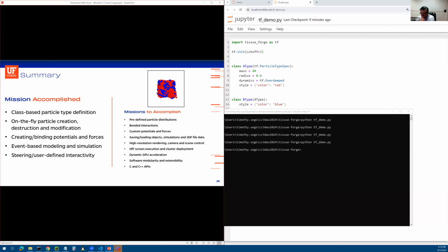So you go at this with finite element analysis, and it's an incremental force that they apply, a tiny little incremental force that they apply to get where they're going with their model. And every time you hit it with an incremental force, it kind of changes the whole shape of the object. So it gets out of control in a hurry. And so I've discovered that if you just take the first iteration, like it tries to iterate off into infinity, if you just take the first measurement, that helps.